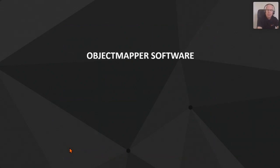Just one thing to note on that one: when you go into the file options on the GPR to upload the data, the first screen you'll go into will be the actual project folder itself, and you'll see all the profile data lines, etc. You need to go up a folder, up a level in the directory, because when we transfer the data, we want to take the whole project and the folder itself.